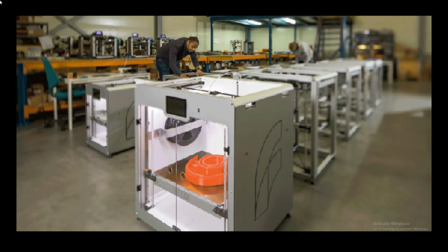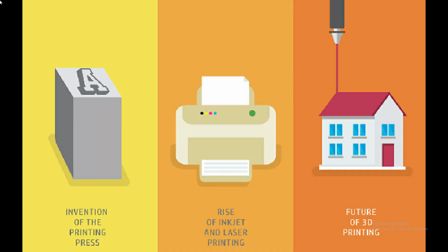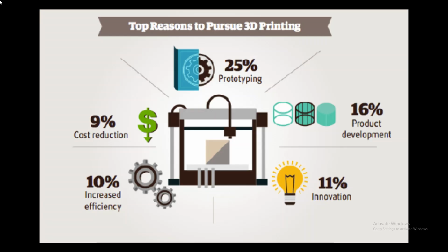The term 3D printing covers a variety of processes in which material is joined or solidified under computer control to create a three-dimensional object, with material being added together, such as liquid molecules or powder grains being fused together, typically layer by layer. In the 1990s, 3D printing techniques were considered suitable only for the production of functional or aesthetic prototypes, and a more appropriate term for it was rapid prototyping.